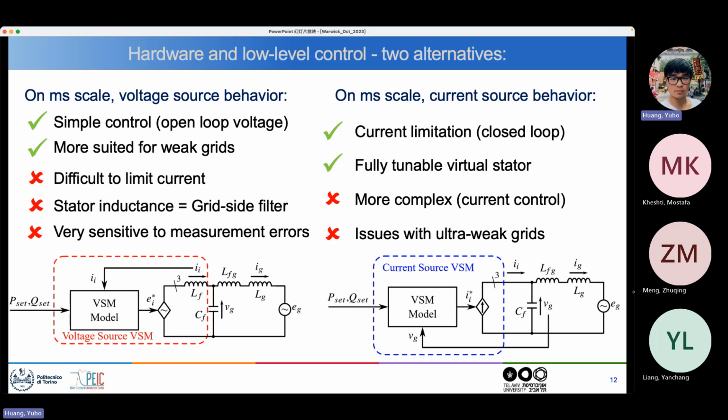One reason is this small impedance: you have to create here a voltage that roughly follows the grid voltage, so that you get a certain power. There has to be a relatively small voltage difference between E, the synchronous internal voltage, and the grid voltage, because the impedance is small. So small voltage divided by small impedance will give you the current that you want.